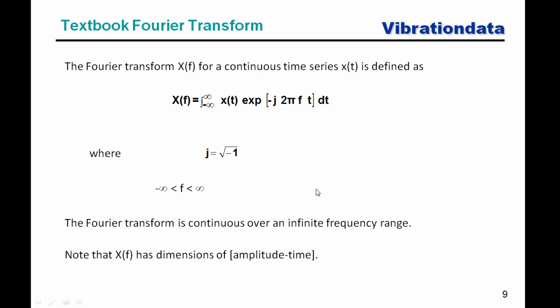So this is an abstraction for us, for engineers, for all sorts of reasons. One of several reasons is that our time histories don't go from minus infinity to positive infinity. We have time histories that are limited. They're finite duration. If we go out and take an accelerometer reading on a vibrating object, that could be for 10 seconds or 60 seconds or maybe 2 minutes or whatever, and we're probably going to start at time 0. We'll probably call our starting time time 0, and then at some point we're simply going to end.